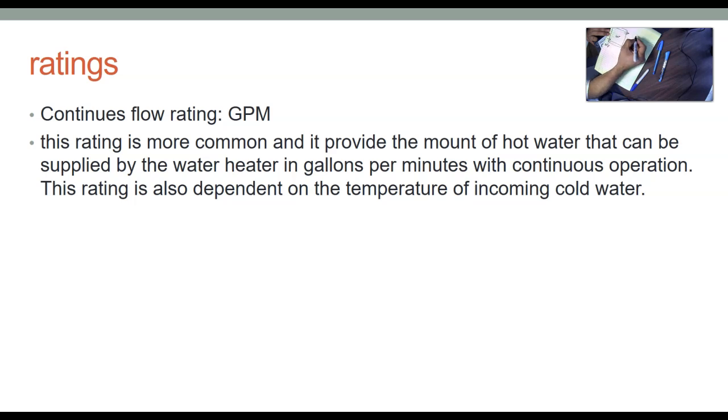And let's say you are pulling water from here and mixing it with city water to get flow rate. So you're going to get 140 degrees, and you mix that with 50, probably through a regulating valve, to get around 90 or 100. So what happens here is this water will get spent. The first few minutes you'll get 140, then this water will mix with the 50, and depending on how fast this tank empties, you're going to get an average of 140 plus 50 over 2, so 190 over 2, which gives you around 95 degrees total, which again is not that bad.